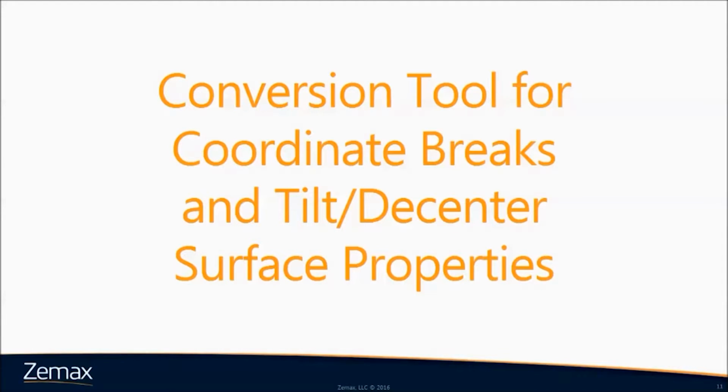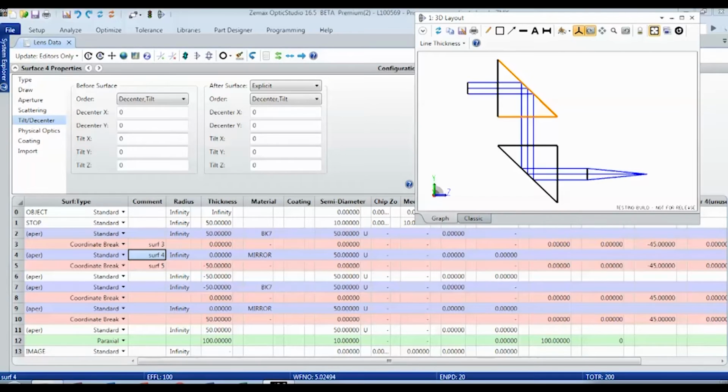Next, we're going to show you a tool that you can use to convert between coordinate break surfaces and the tilt and decenter settings in your surface properties. OpticStudio 16.5 has a new tool which allows users to easily convert back and forth between coordinate break surfaces and the tilt and decenter section of the surface properties.